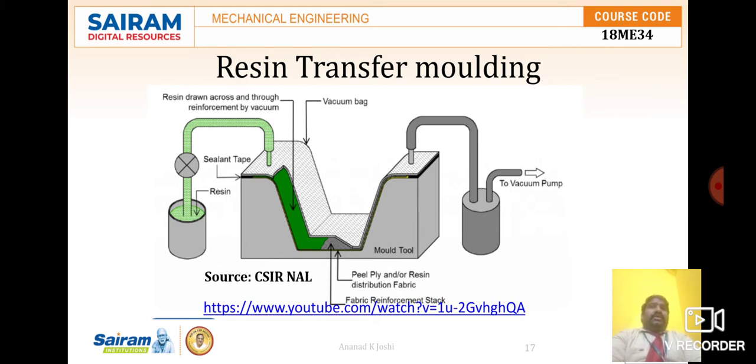In this molten state, a plunger mounted on the top plate moves downwards by a controlling valve, pressing the plastic charge and forcing it to transfer into a mold cavity through this screw. The mold is equipped with a heating system and provides curing of the polymer composition. Then the mold is opened and the part is removed by means of an ejector pin.